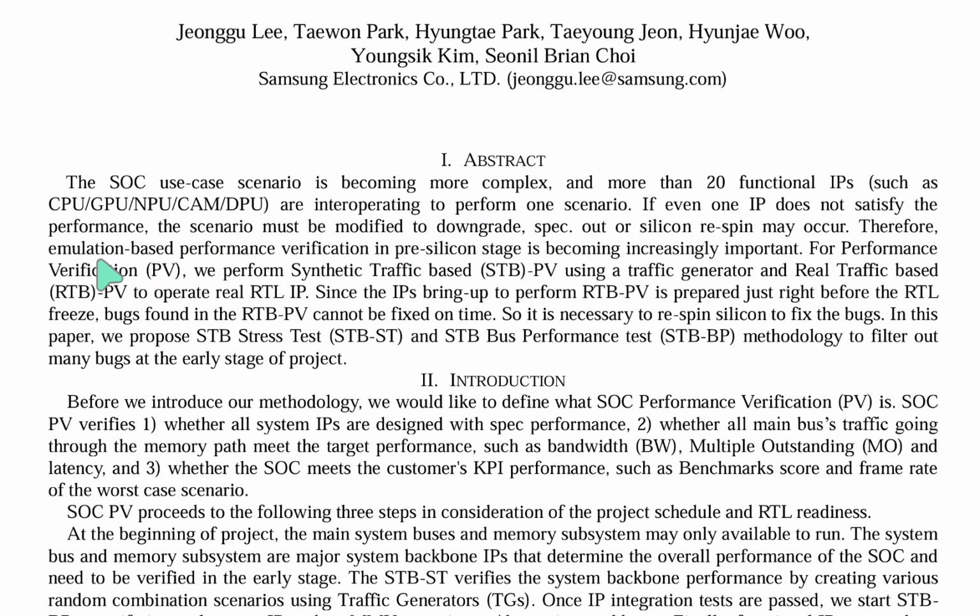Therefore, emulation-based performance verification in pre-silicon stage is becoming increasingly important. For performance verification, PV, we perform a synthetic traffic-based STB-PV using a traffic generator, and real traffic-based RTB-PV to operate the RTL IP.